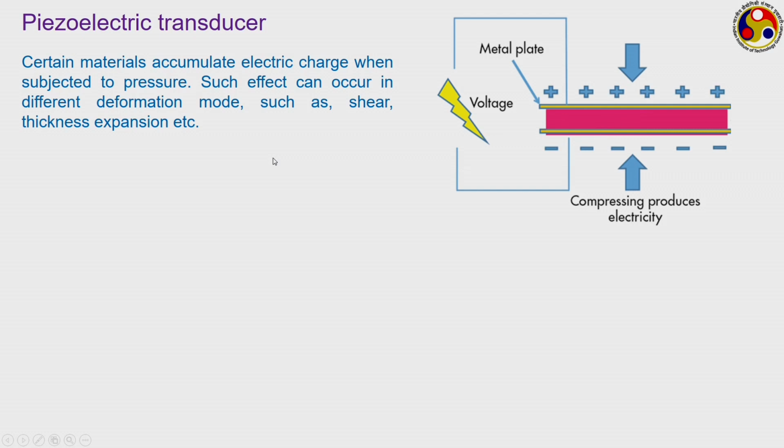Like if this red one is a piezoelectric material, some kind of piezoelectric crystal, then when you subject it to some kind of compressive or tensile load, depending upon the magnitude of the load, a proportional amount of electric charge will be developed, thereby creating a potential difference across the two plates or the two sides of the crystal. We can measure this voltage, and that can directly give you an idea about the amount of force that you are inducing onto this, and that force can subsequently be related to the displacement of the plates.